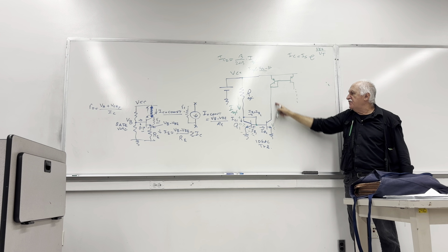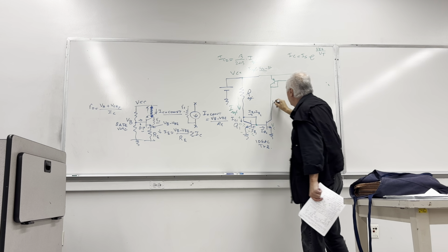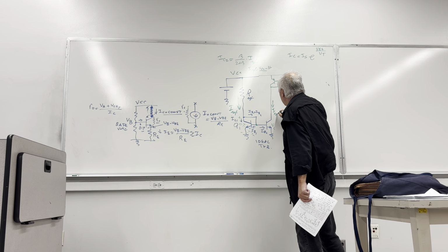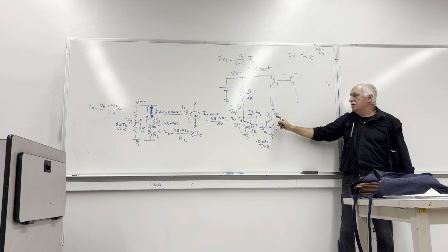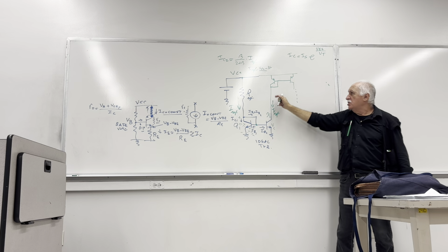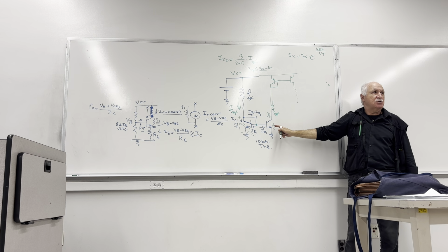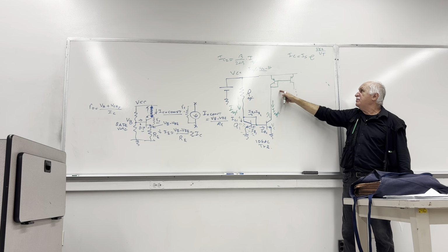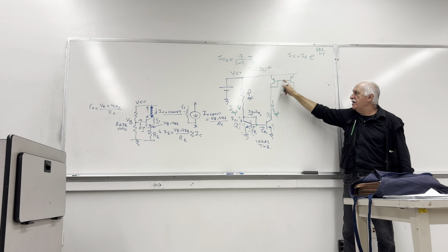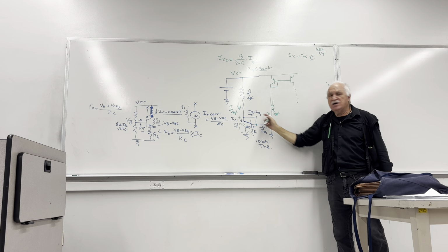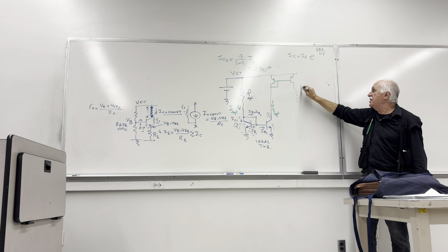See, you need a reference in here, Iref approximately. Because that branch, as I said, is equal to the current over there. So we can create that current in this branch. And that PNP transistor, which is wired exactly by the same philosophy as the lower one, will create Iref in here.